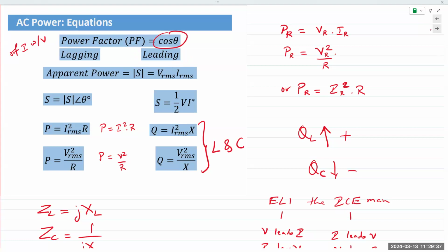No. It depends on the component and on the circuit. Are you referring to lab 6? It was a series circuit, and all components shared the same current: the source, the resistor, the inductor, the capacitor. So to apply KVL, that phasor diagram was the summation of all 4 voltages. You could apply KVL to that loop because it was a series circuit sharing the exact same current. To draw that phasor diagram, we plotted that current with a phase angle of 0, but we don't actually know what that phase angle was in real life. Does that make sense?